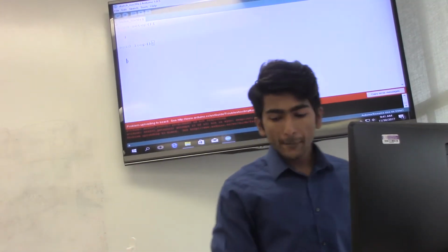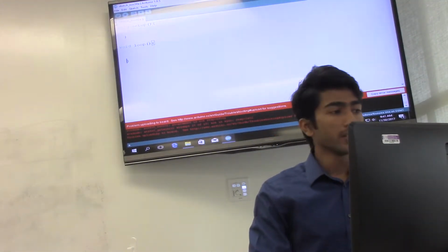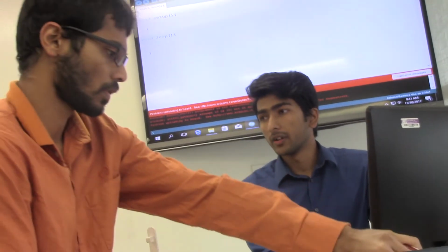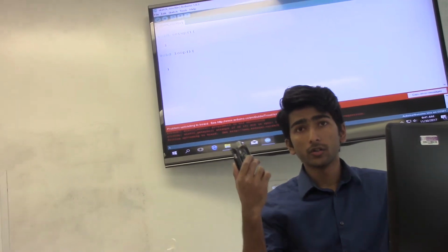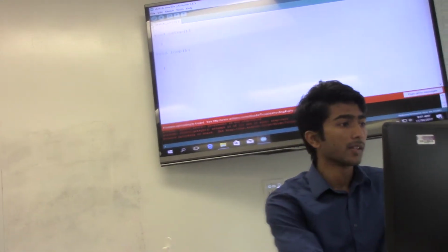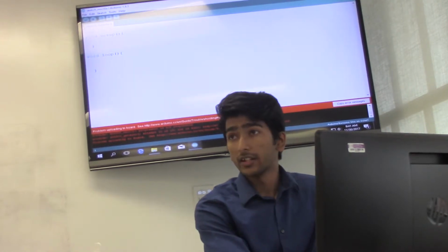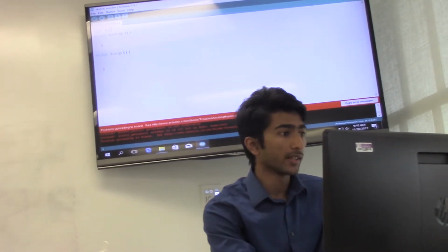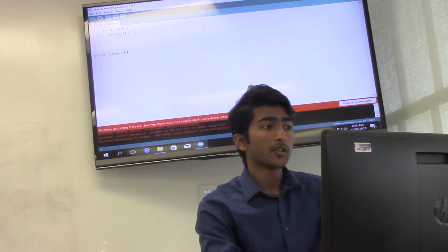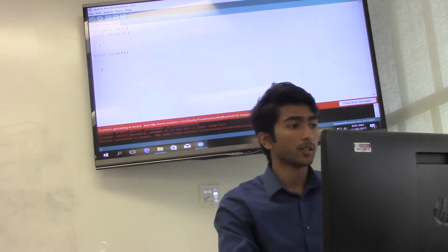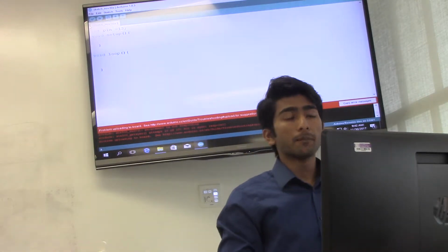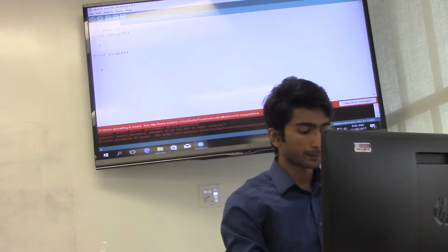So let's do a demo program here. What I'm going to do is create a variable for pin number 13 on your Arduino kit. So the way that you define variables is give the data type. In this case, this is integer, and then I'm going to call this pin, which is just a name, and I'm going to give the value 13. So here 13 is stored in the variable pin, and for the first setup, I need to set the pin mode to output.